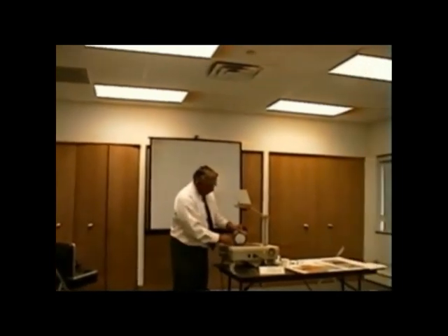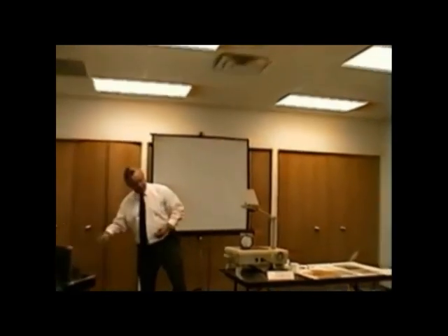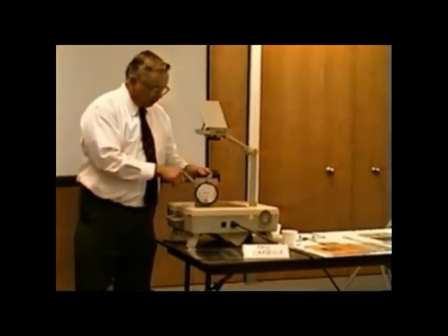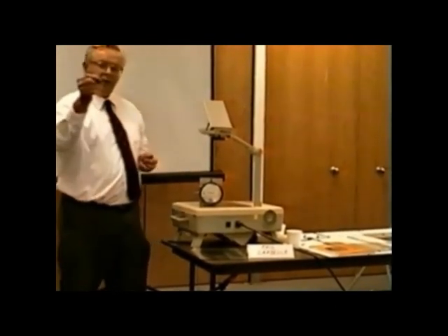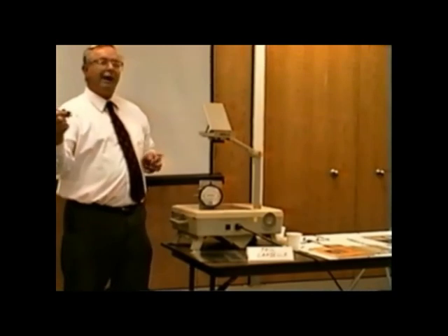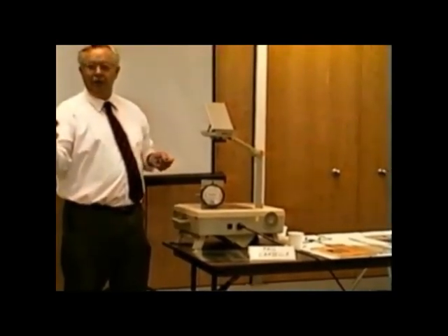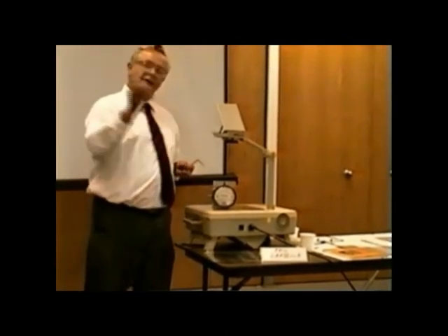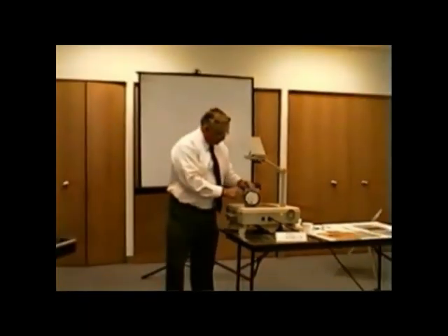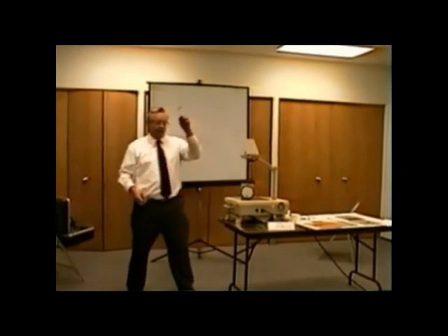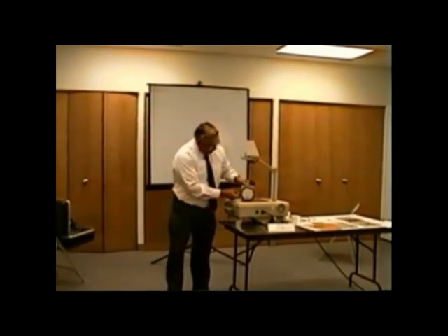We're saying that we want to use the magnehelic. Now, we showed you before that you have a positive on top and a negative on the bottom. So we want to stick a hose on the positive, stick it on the probe, and which is the positive ductwork? Supply or return? Supply. Okay? So we want to take this and stick it into supply. So you're going to attach it here, and your hose is going to go into your supply. The return, it's sucking air into the furnace, it's negative. So this one gets attached to the negative port, and we stick that into return.